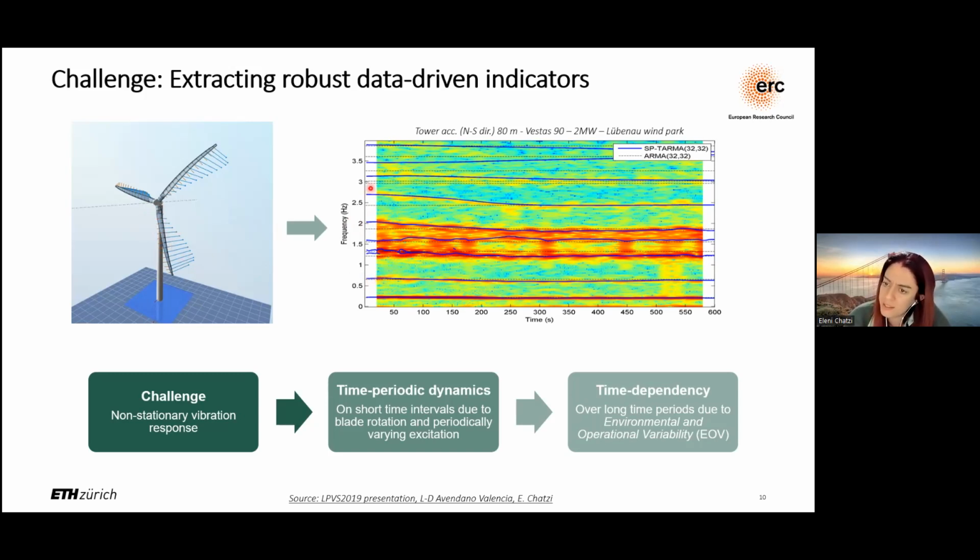And you see that if we look at the frequency range, we do not have a constant spectrum, or stationary spectrum, which means that we here are dealing with a time varying phenomenon. We have a modulation of the dynamics of this turbine over time. This is a 60-minute interval, and the modulation is due to the dynamics, due to the interaction with the wind.